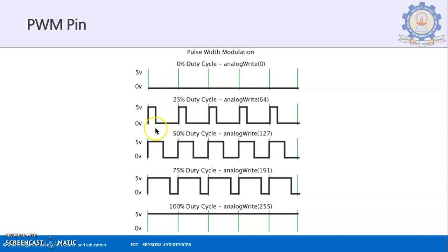Okay, so that is why to our human eye this width will look long enough, but please remember this is only 1.5 milliseconds. By the time you think of snapping your finger, the time is gone. Okay, so that is 25%, this is 50% over here, and the next one is 75% over here. So 75% duty cycle means on time it is going to be 75% and 25% it is going to be off. On time it is 75%, off time it is 25% over here.